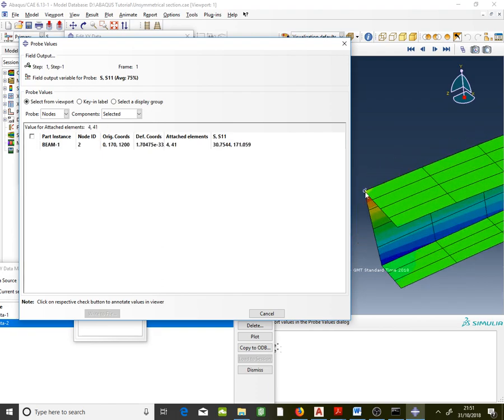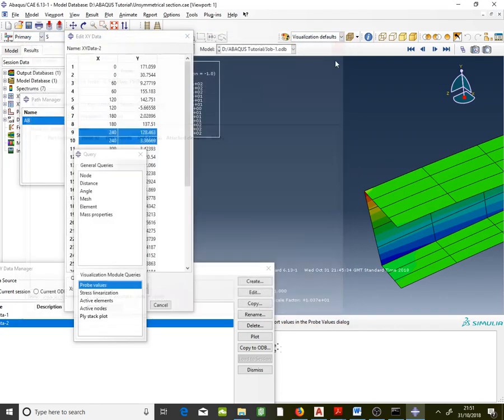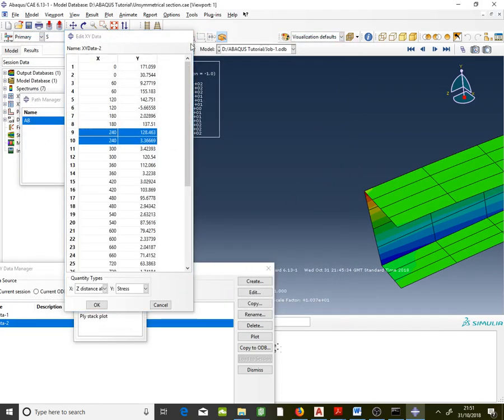Again the same here, you will have 2 values, one from the flange and one for the web. Now what you have to do, over AB choose the maximum values, and this maximum value represents the bending moment over AB for the web. So in this way you need to choose 171.059. Okay, now close this and back to this point here.